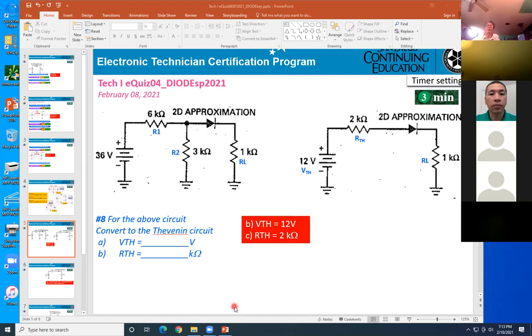Okay? And if you want to calculate the R Thevenin, same thing. Remove the load. And you're supposed to get the current flow in. I thought you had to short something. Yeah. Mr. Pham, short circuit. I thought you had to short the battery. I thought you had to take out the power, like the 36 volts here. No, you remove the load, right? The open circuit, that will be voltage, and the short circuit current.